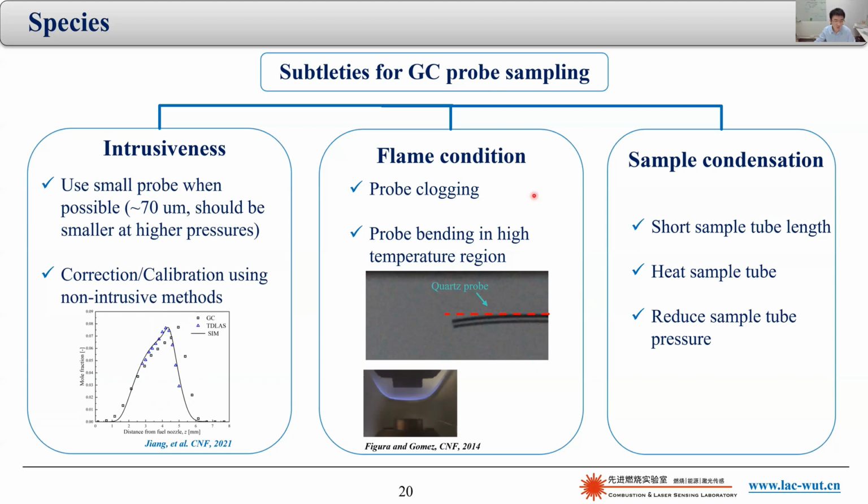In sooting flames, you also have to worry about the probe clogging, and once that happens, you have to remove the probe and send it to an oxidizing environment to burn it off. So actually, this type of experiment is quite time-consuming. Another issue is in the high temperature region, where you may also have probe bending because the force